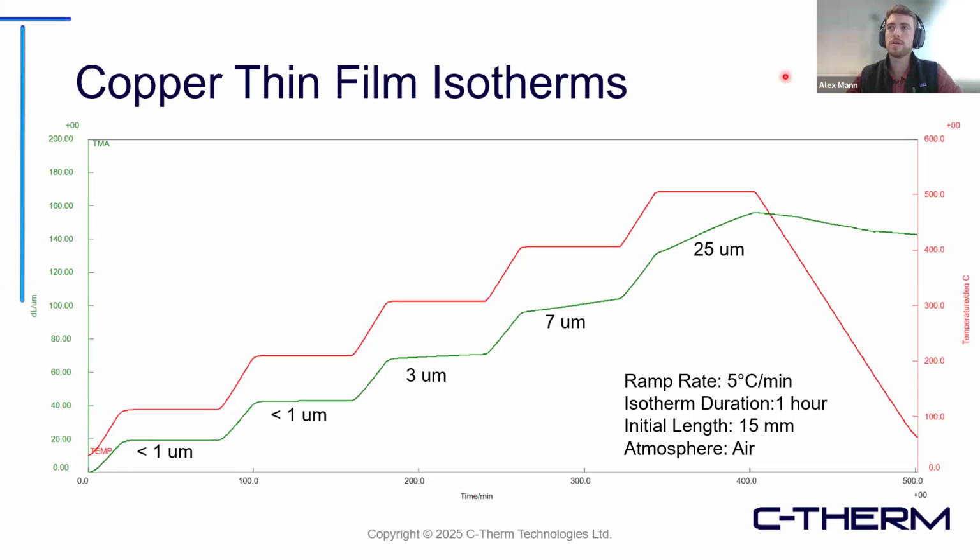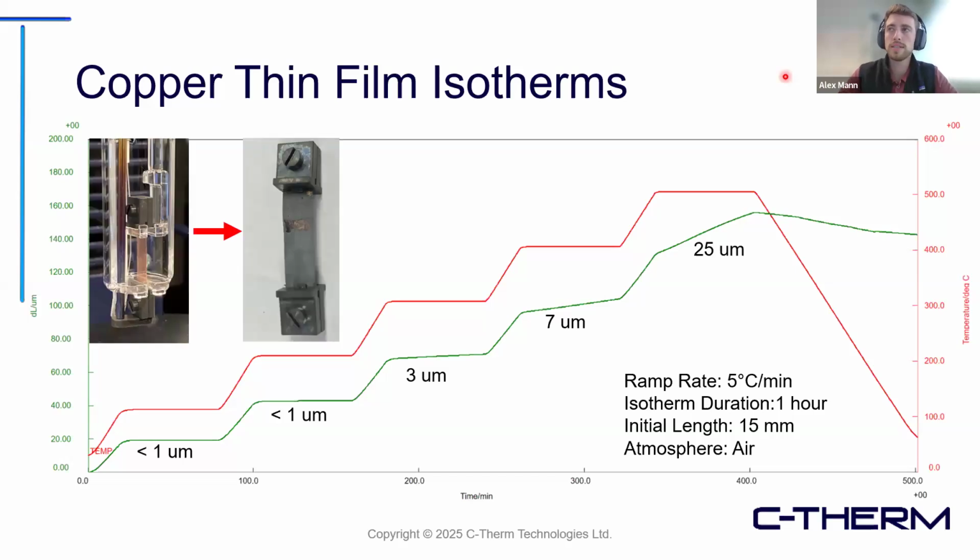Essentially what was happening is the copper was oxidizing as we held it longer in the furnace, and then right here we can see on the cool down, it didn't return to normal because it had taken irreversible damage from the oxidation.